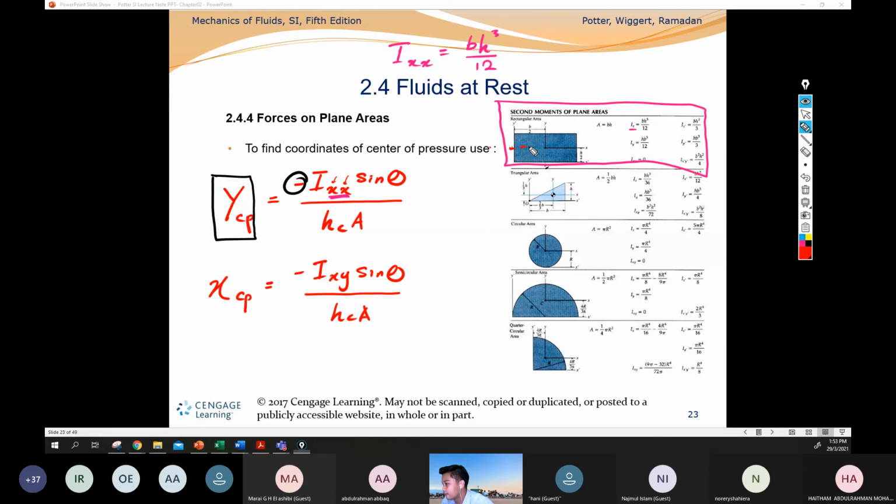The moment will be in this direction, just as an example. It tries to bend in the XX direction. So the formula to get I_XX is b h cubed over 12. What is b? b is this one, and h is the height, over 12.